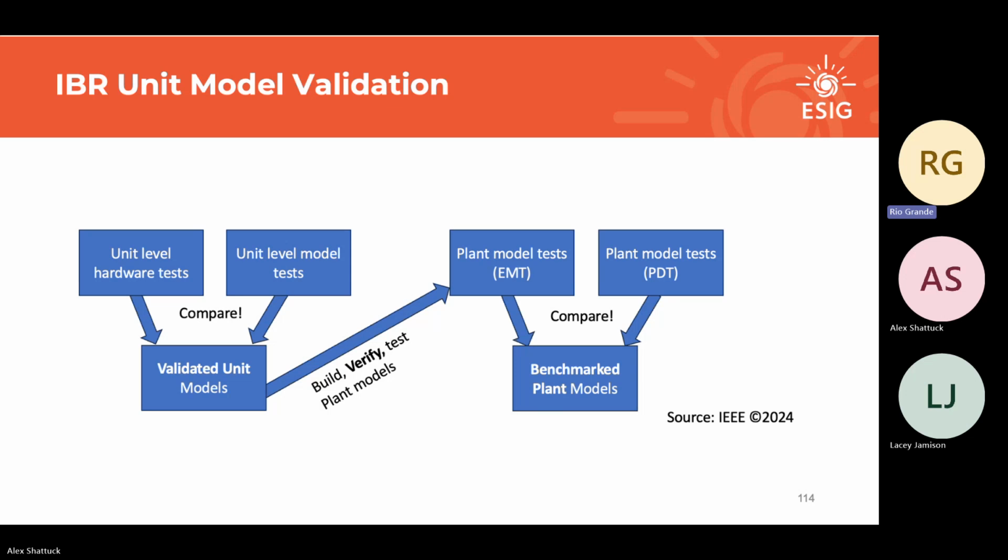So it's not just the traces and the P and the Q and the V, the voltage and the power and the reactive power that you're measuring. When you're doing unit level, inverter level hardware tests like this, you're looking at everything, right? You're recording exactly the profile that you played in, exactly the parameters, conditions and measurement errors, and you're getting back from the actual product much more stuff that we'll never see as end users, like flags of faults, or whether you entered a mode or not, and things like that. So those are used on the back end by the OEMs to validate their models.